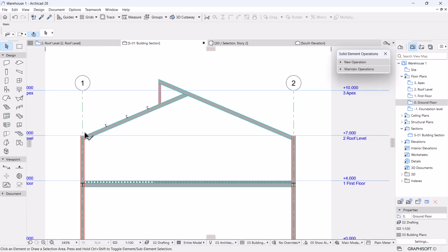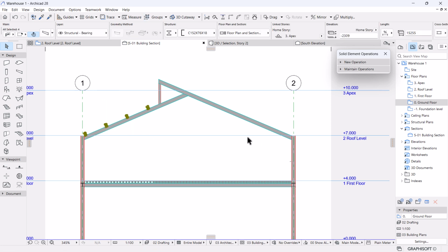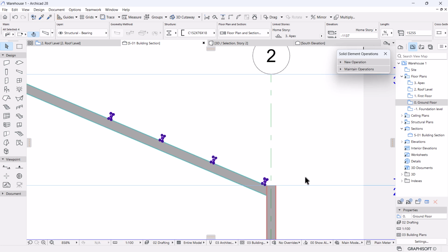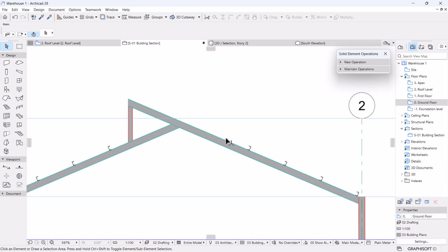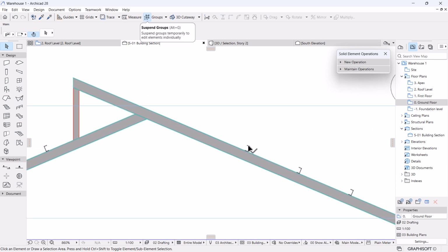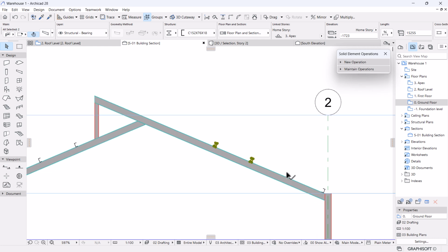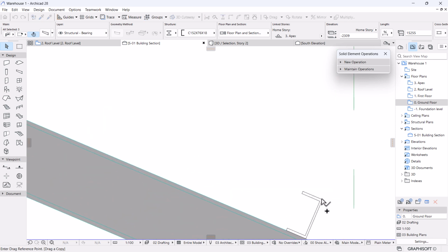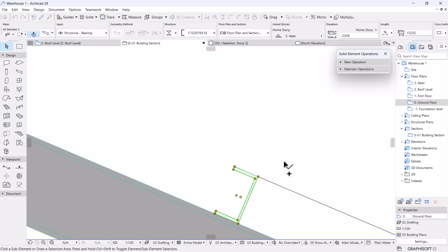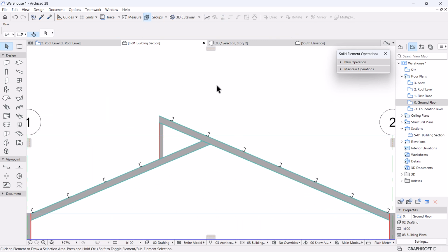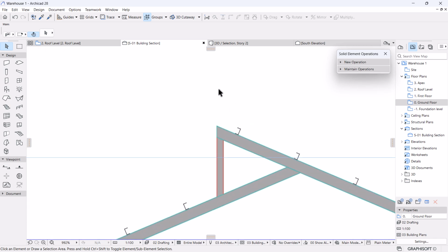Then I'm going to copy this to the other side. Control Shift D on your keyboard to mirror it to the other side, right? We have it there. Yes, and then we can complete the remaining part by duplicating the other ones. I can pick these 2 because I will need 3 there. Control Shift D, I'll use this as a copy point to this one. Right, perfect. It's nicely done.